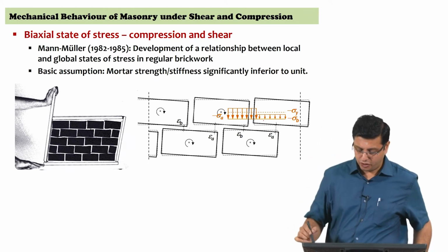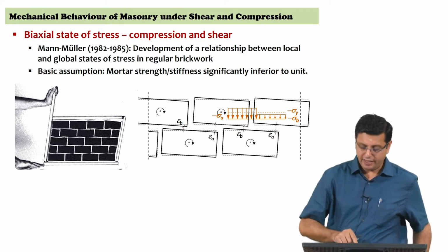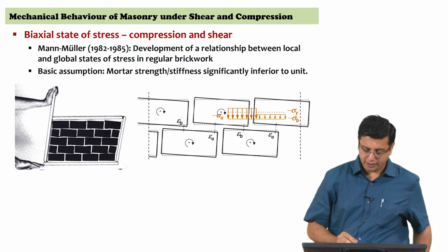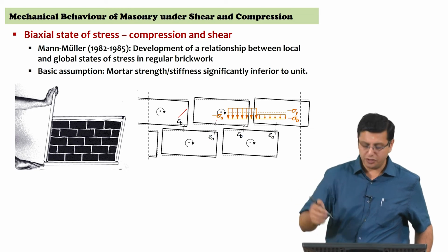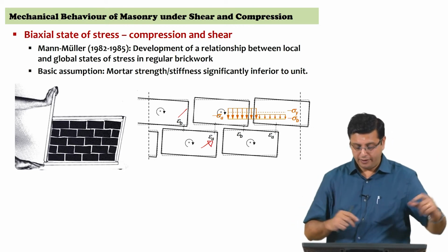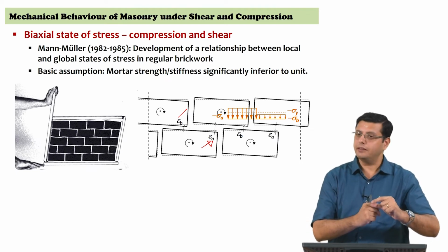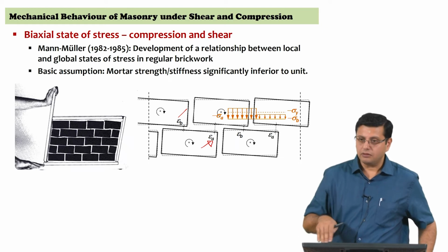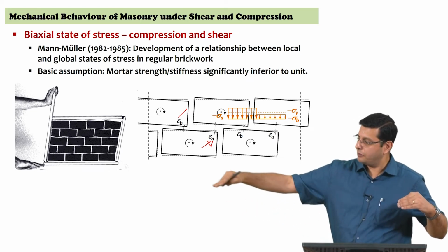So, if you were to examine the joint, there is strain in that joint, epsilon B, when the mortar joint is getting compressed, whereas in the other case where the mortar joint is opening up, it is more than what it was originally. Epsilon A is that quantity of strain in the joint where you are getting the reduction in the level of compression because of the rotation of the unit itself. So that is examining it in terms of the strains, the deformation and the strains in a mortar joint. So this is going to keep happening wherever there are units.